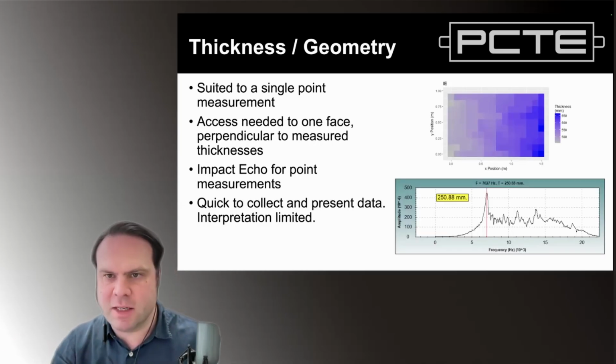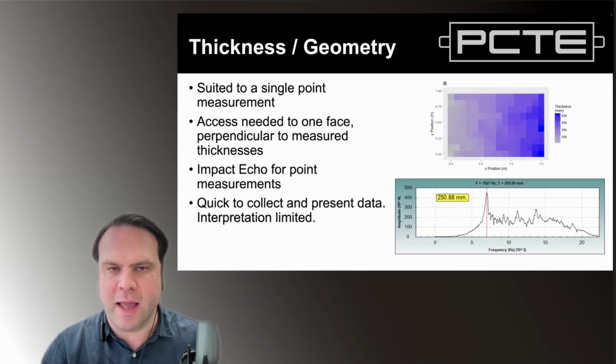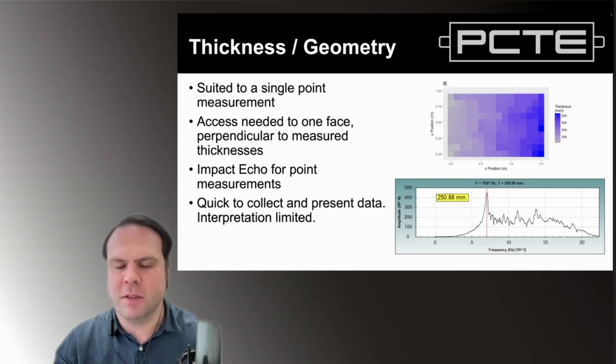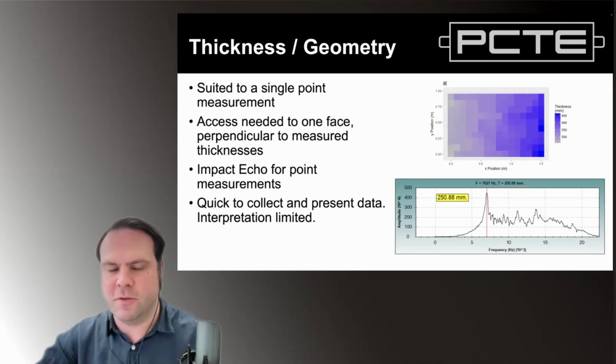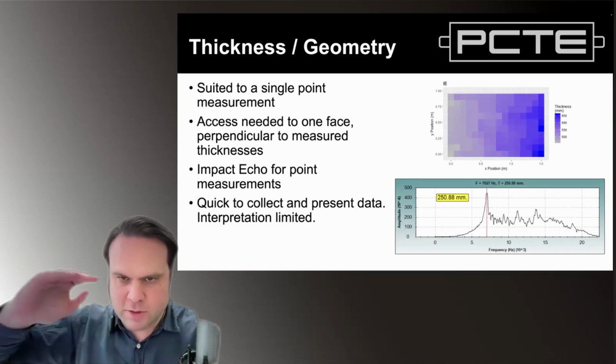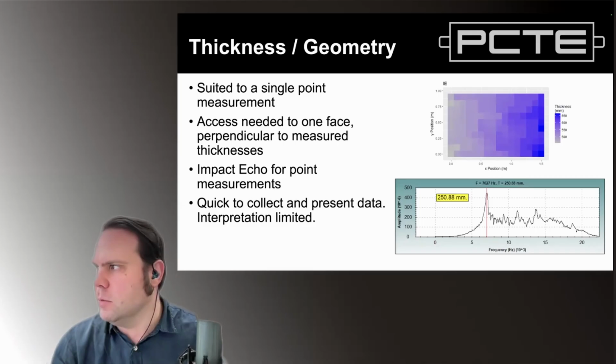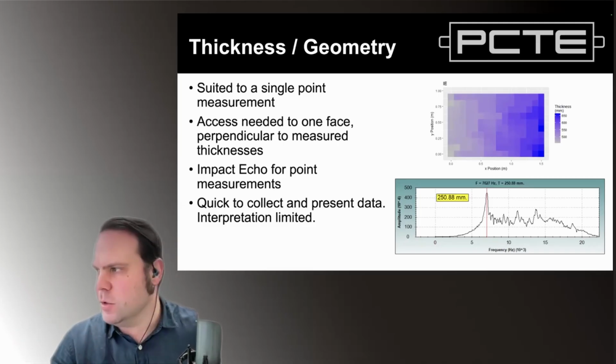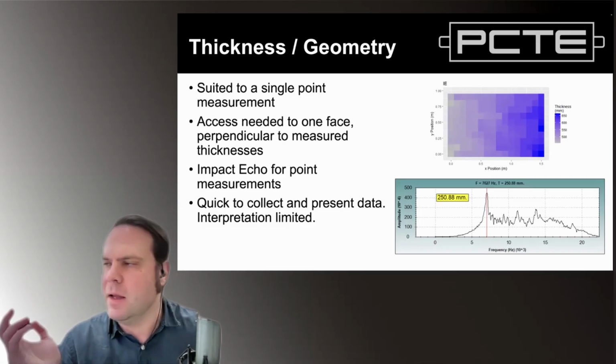So in this first example, this was on a concrete slab next to a boat ramp. So the concrete thickened as it went further along the boat ramp, as there was more distance to cover. So we measure the frequency as normal. We convert to a thickness, so 7,000 hertz, 250 millimeters in this example.